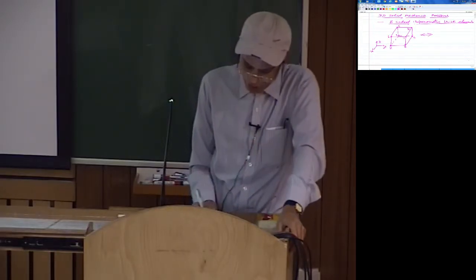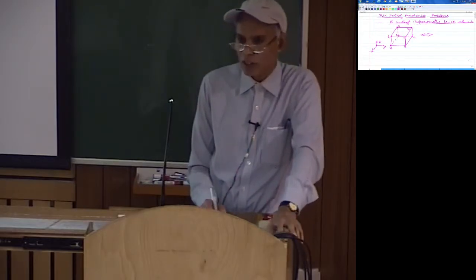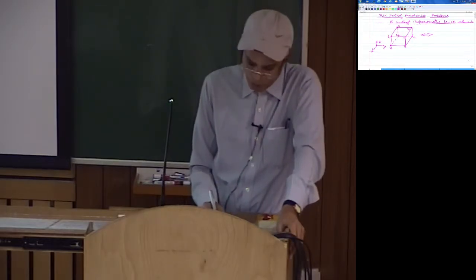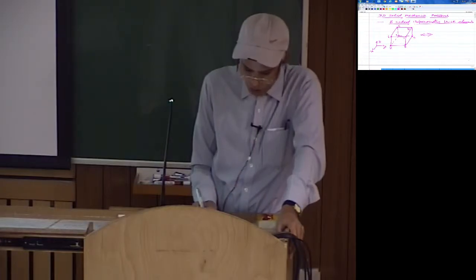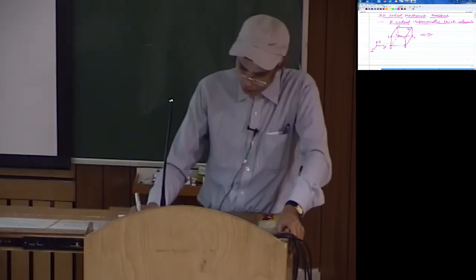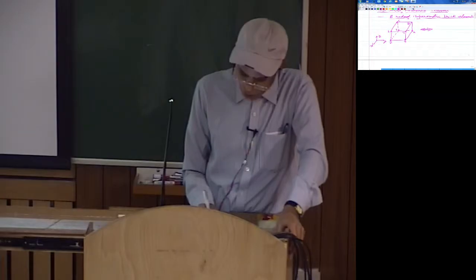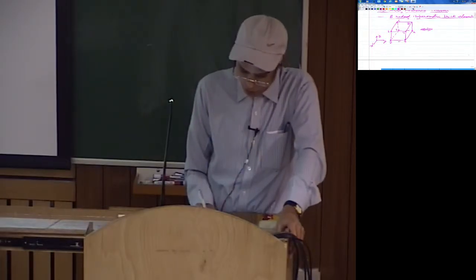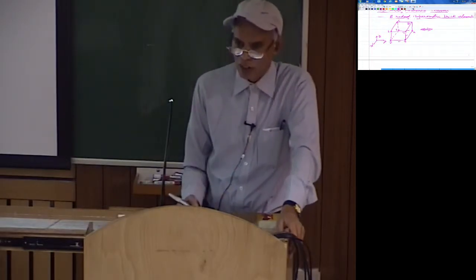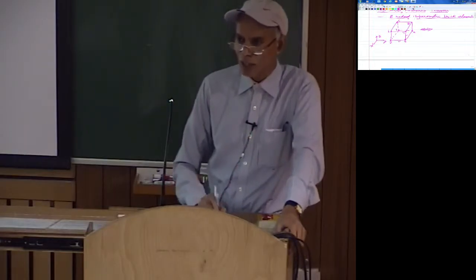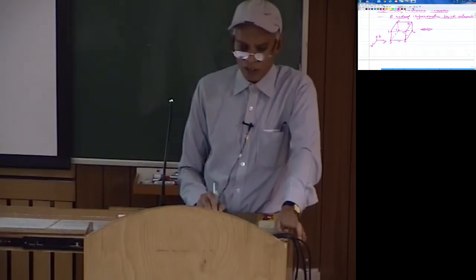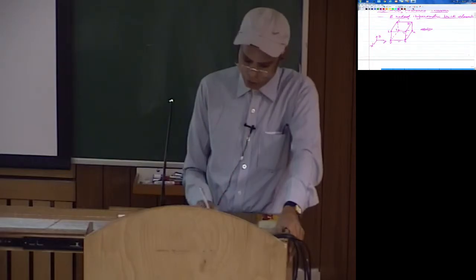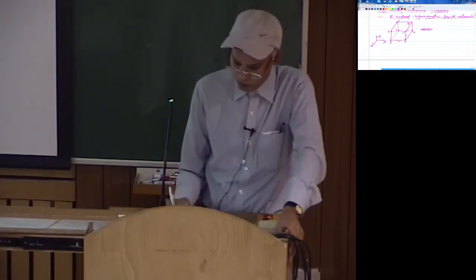So here, as I said, these angles in general can be anything. Of course, ideally this would be 90 degrees as we have studied earlier, and for the edges also, the aspect ratio, that is the length of this edge to this or any other edge, theoretically can be anything. But ideally, from the conditioning of the Jacobian matrix, this ratio should be unity.